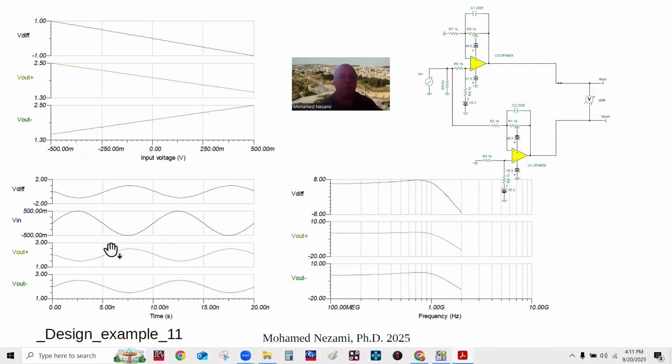So let's put this very same circuit on the simulator, and that's what we get in here. Let's go to the simulator so we can see it better. We have the circuit here, and the input-output relationship DC-wise, because this is DC coupled. One of them has a positive slope and one a negative slope, so these are differential. When we subtract them, we end up with this, from minus 0.5 volts to plus 0.5 volts, which gives you from minus 1 to 1, which is what we need.